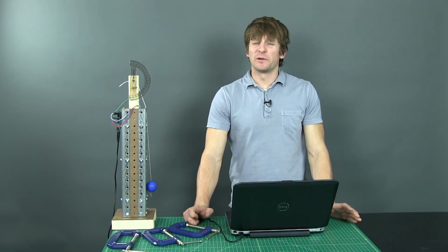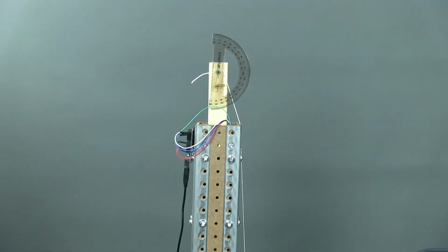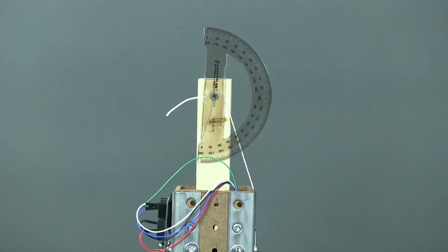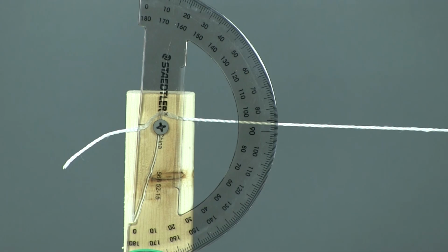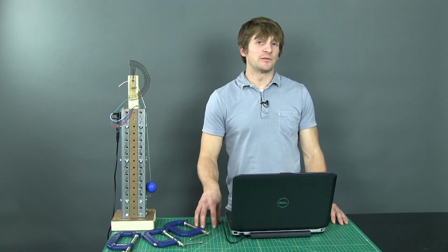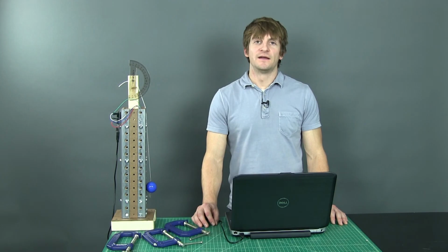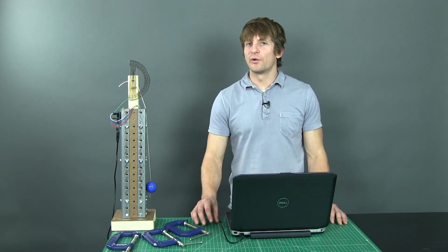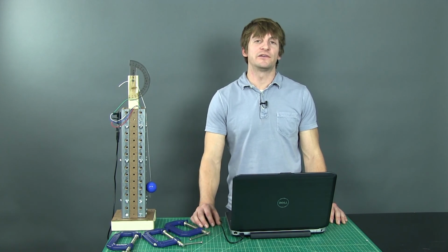By approximating an arbitrary potential energy function with its Taylor series expansion, we were able to make the claim that any structure, no matter how complicated, can be modeled as a simple pendulum for small oscillations. We have just verified this claim by performing an experiment on a scale model building and analyzing the data from that experiment. We should note that being able to determine the spring constant of complex structures is a very powerful result in engineering analysis. Taylor series approximations allow engineers to approach this analysis in a straightforward and simple manner. And because of these models, these engineers are able to develop optimal solutions to these complex problems.